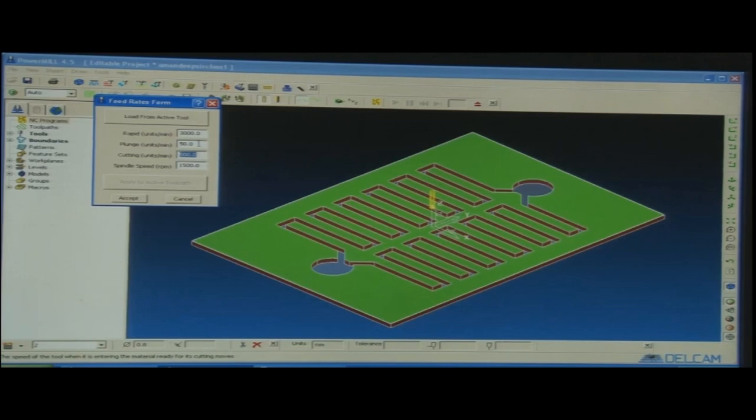When I say final machining, it has to be the feed rate that is selected for the specific combination of the tool and the workpiece. For instance, we can use the chrome plated tool for mild steel. So, there is a specific combination of tools. Some materials are very hard, like titanium. For titanium we have a specific set of feed rates and plunge rates as well.